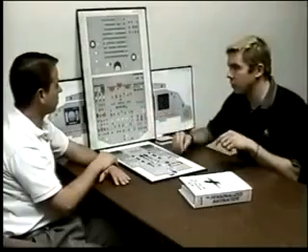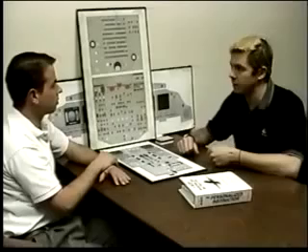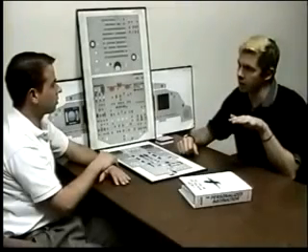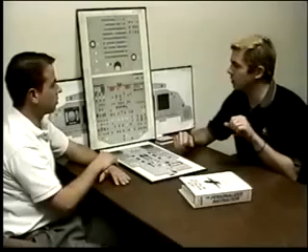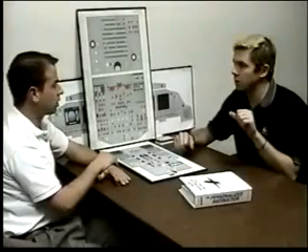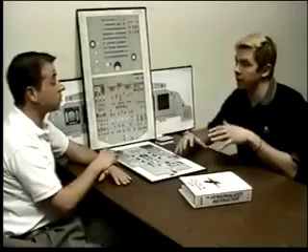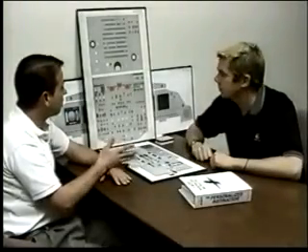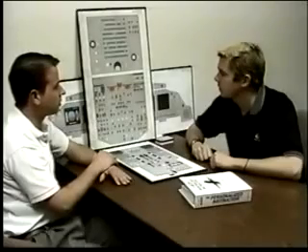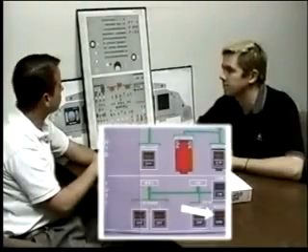The fault light illuminates whenever the center tanks are greater than 550 pounds and the wing tanks are 11,000 pounds or less. Would the center tank pumps be operating? The center tank pumps would be off in that case, and they should be operating. So the auto feature has failed. How would you continue to burn that center tank fuel? I'd select the switch to manual and allow it to run just like the wing tanks.